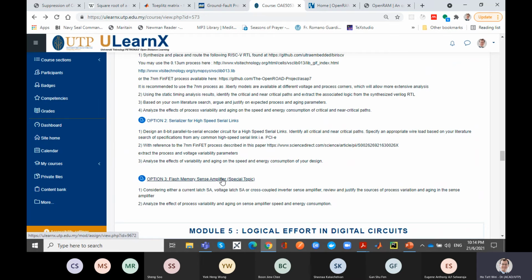That's the point of all of this, that you can look at the critical path and go, I know I need to fix this. What are my options? One of the more straightforward options is you just do logical effort sizing. You change the width and all that to speed it up. The next option, of course, would be a bit more heavy lifting. You start changing the logic, then you use logical effort again to see that.